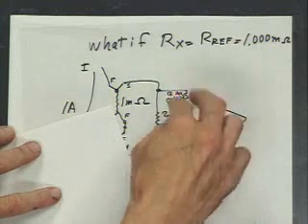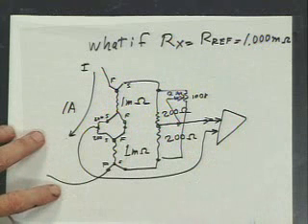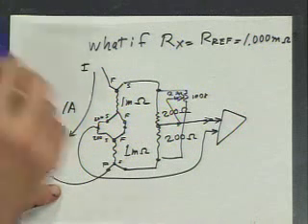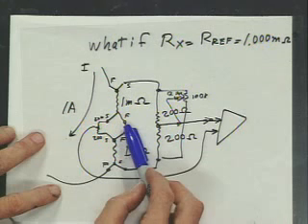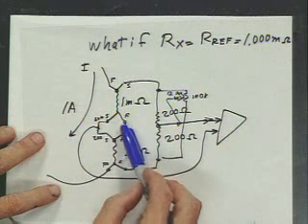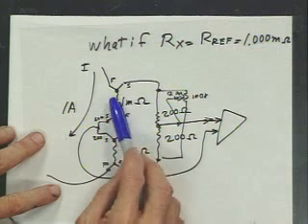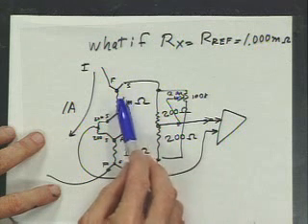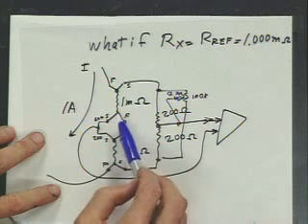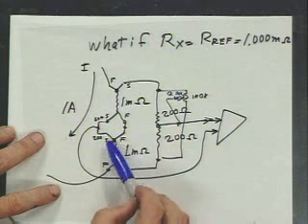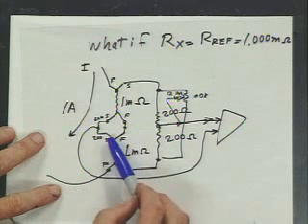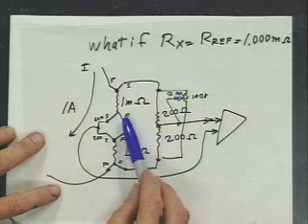But if we just connected the other side of the amplifier to here, it could cause an error. How? Because you might have 1 millivolt here, 2 millivolts here in the sense connection to the resistor. The higher drop in the connection could cause terrible error.